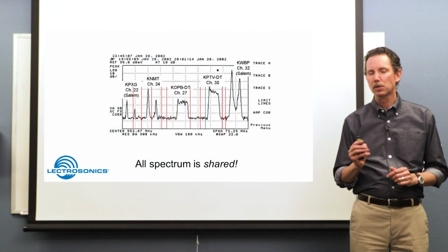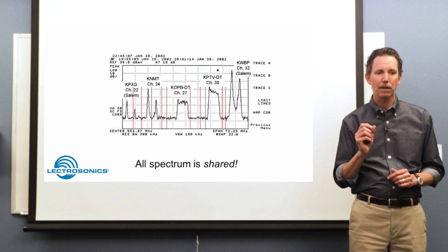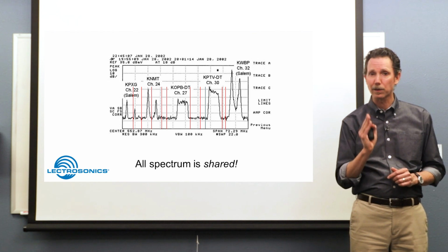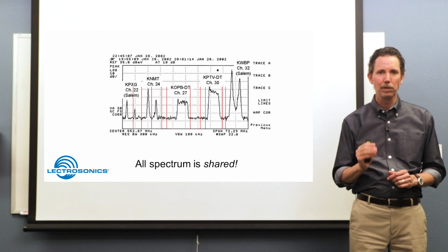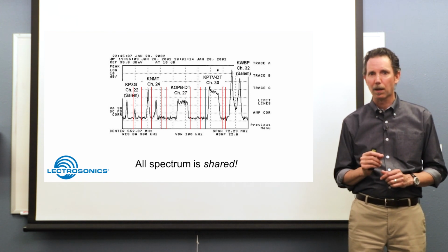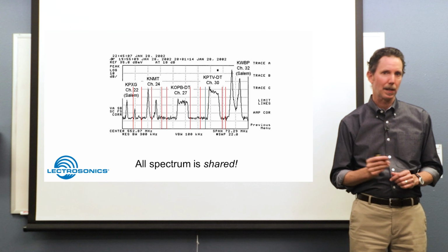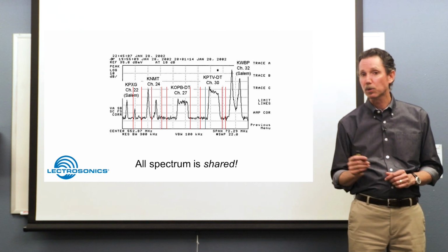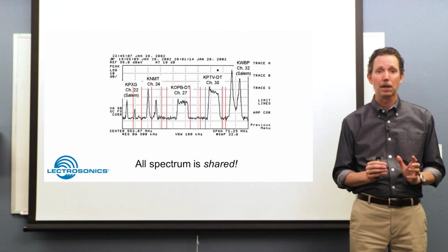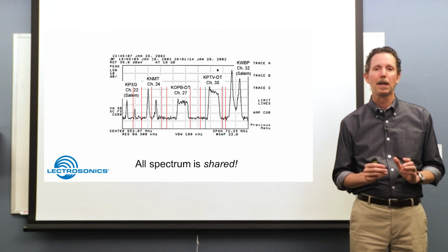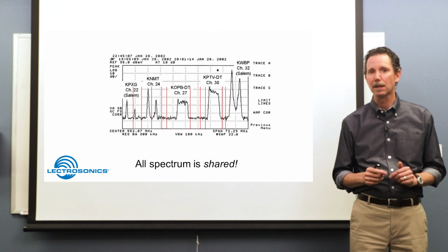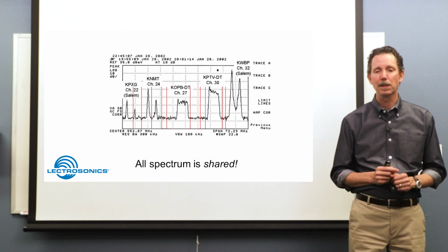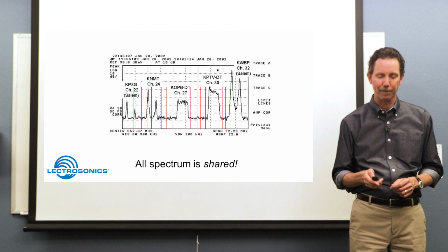So where do we fit in? Exactly in between those. Those red lines are what are called carriers, our wireless frequencies that we're using. We've got to find open slots in between TV channels to put our wireless microphones and in-ears and communication systems. So it becomes quite challenging in dense areas where there's a lot of TV channels and we have a big production we want to put on using a lot of wireless mics. As you can see, it gets very tough. And we'll cover this in a lot of detail, just how to do that.